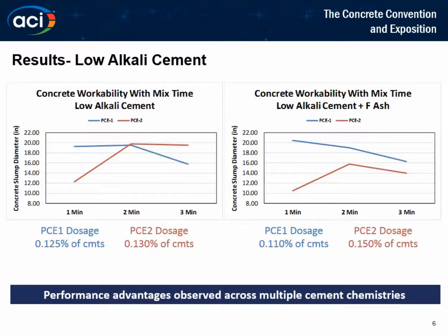It makes sense. I'm just curious if you actually discharged it at that 1 minute, and let's say it went into a bucket at a precast plant. Would it then lose some of that based on this result? That's my question. No, we haven't seen that, especially for precast, because the mixing time they can reduce. The precast case study is a good example of that. They are able to reduce their batch time without sacrificing the plastic performance. It doesn't go away so fast that they can't get it placed into the forms effectively. It's not rapid slump loss.